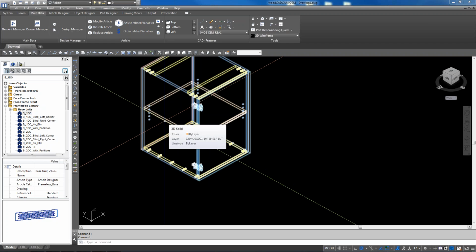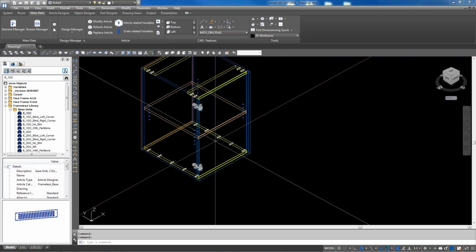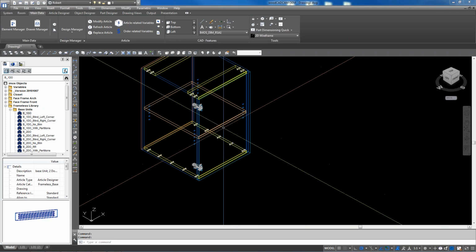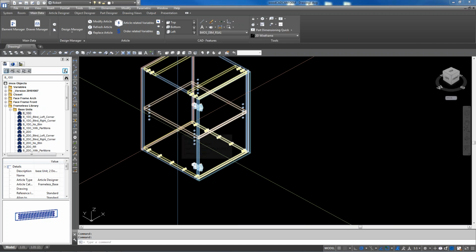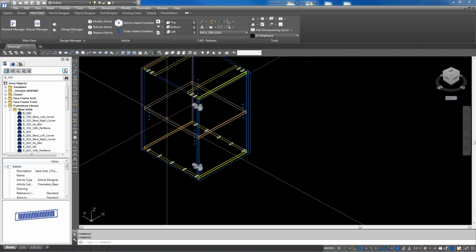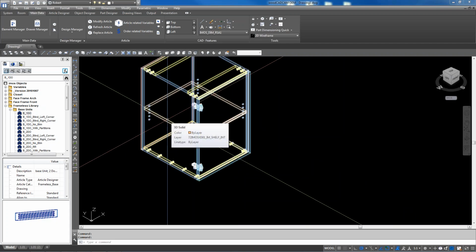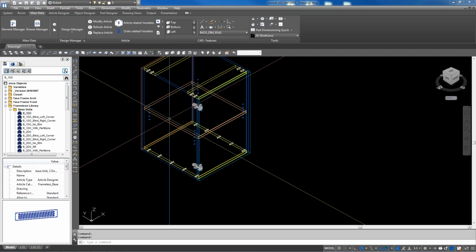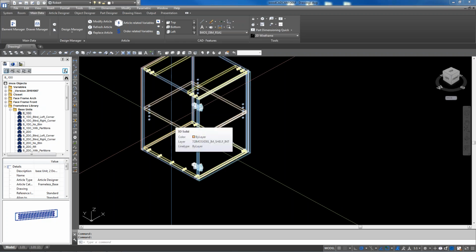Okay. Does that make sense to you, Robert? It does. You're not really affecting your construction. You're just changing out which side panels are being used, which shelf's being used. That's all. Right. And then the holes are assigned to the shelf instead of to the cabinet. Yeah, the holes are actually assigned to the shelf pin or the shelf clip, which are on the edge of the shelf. Okay. Instead of to the cabinet. So if you were to take this shelf out, then you would get no holes because they're part of the shelf. Right. Versus the full line boring, as you know, if you don't put a shelf in there, it still has the line boring.